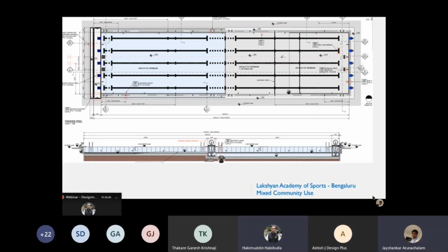In this specific case, the bulkhead comes up to the bottom, and the depth over here is 2 meters. So here it's flat and it gets parked over here, so that there's no room for any entrapment. If the bulkhead had to go into the shallow area, then it would have to be only 1 meter in height, as you can imagine. And when it moves into any of these areas, which is 1.35 meters, it can create an odd space that can create a risk of entrapment.